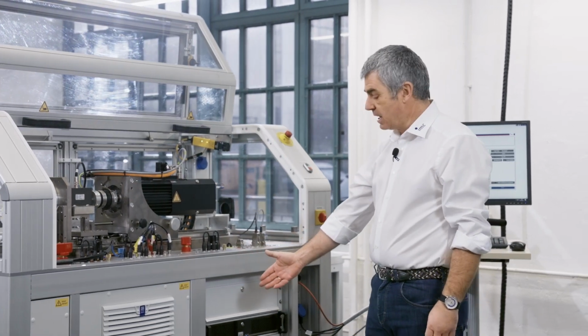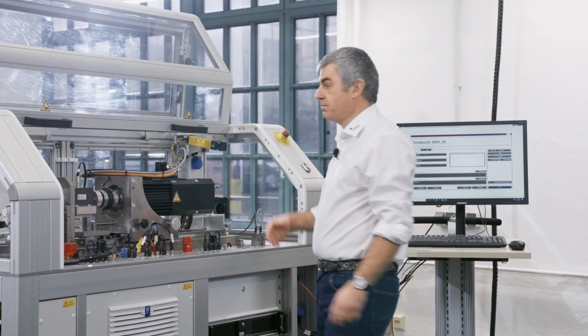Hello and welcome. In this video, we will show you the process and evaluation of the static performance curve test type. The control of the motor can be checked with the characteristic curve test, and the efficiency and the ID/IQ current mapping is verified. This is an active test, which means that the DOT is supplied with the configured phase current and voltage by the inbuilt controller.